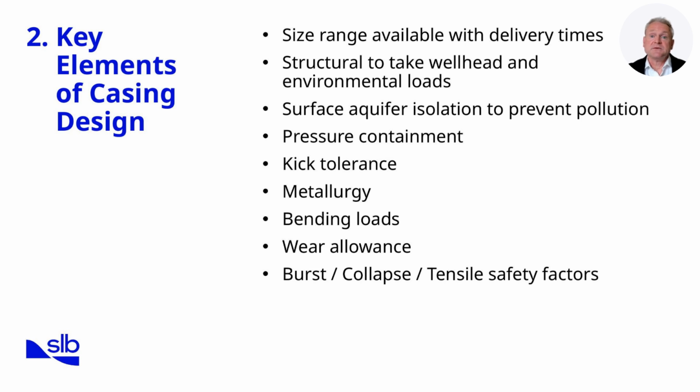Next, casing must provide structural strength to support the wellhead and withstand environmental loads. It also needs to ensure surface aquifer isolation, preventing contamination of freshwater zones. Pressure containment is a critical design driver.